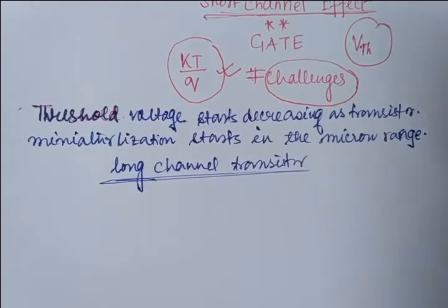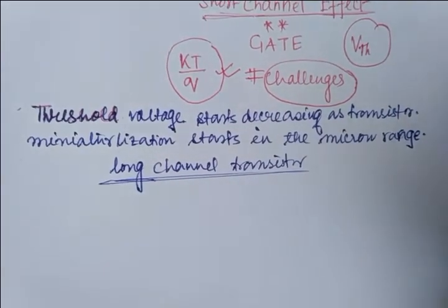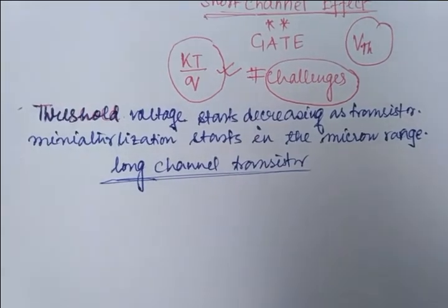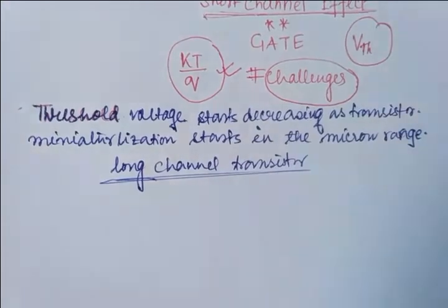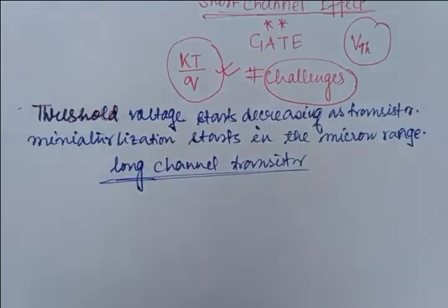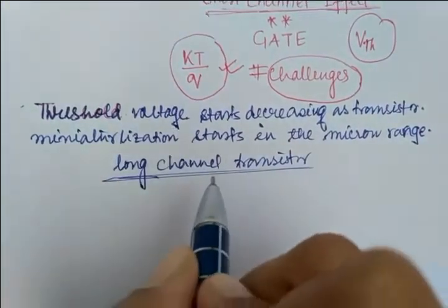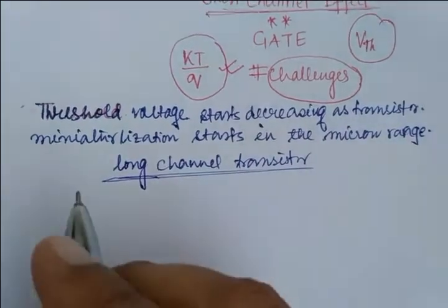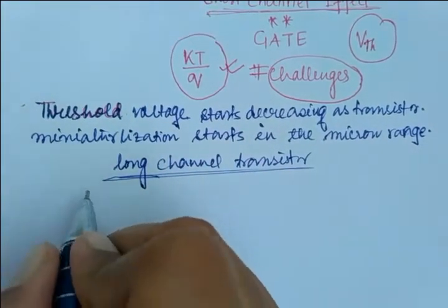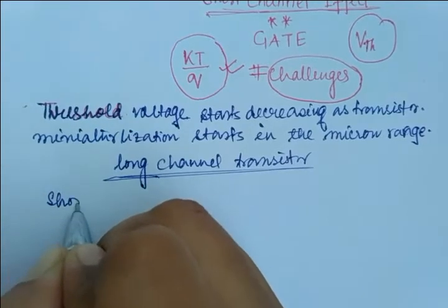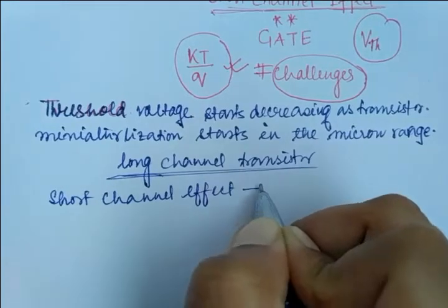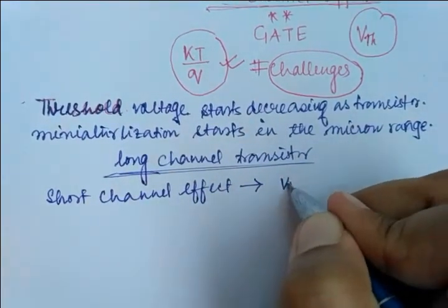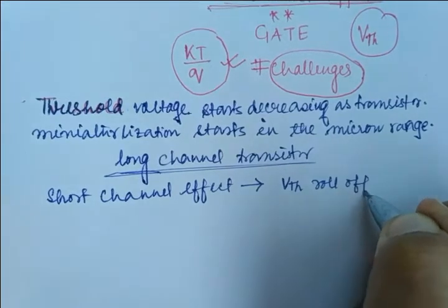I can skip the important things, but from my end as a teacher, it is very important to discuss all the basics at a deeper level. So from the concept of threshold voltage, we will discuss the short channel effect, which we can also express as VTH roll-off.